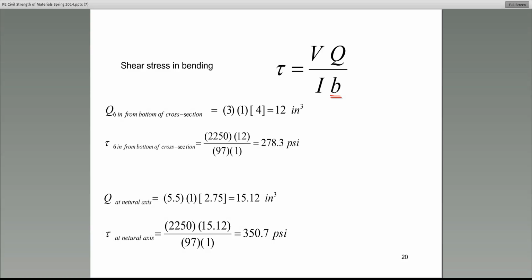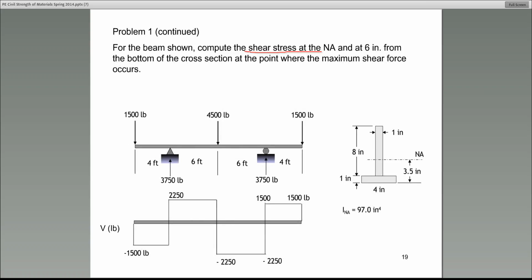All right? Now, this concept of width of the cross-section is interesting because I'm going to go back and ask you a question here. This is slide number 19. Everybody, please, take a look at slide number 19. Let's assume that Jonathan says B is the member width. That's correct. And sometimes some books use the letter T instead of B. It doesn't matter. It's no matter what they use, it is the width. All right? But tell me, for this inverted T section, and we will do it together in just a minute, what would you use for the value of B, the width? What do you think?